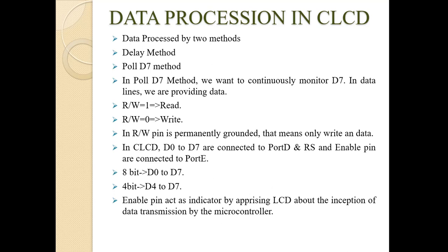If the R bar W pin is 1, then it will perform the read operation. If the R bar W pin is 0, then it will perform the write operation. If the R bar W pin is permanently grounded, that means only write and data.